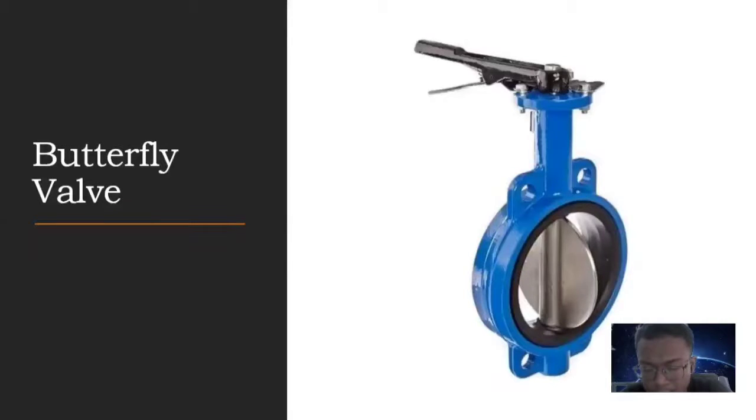Butterfly valve. A butterfly valve has a circular disc that can be rotated through one complete revolution. The circular disc has a diameter equal to that of the pipe. The valve is connected across both faces by two pipes with flanges. The circular disc is made to rotate around an axis passing through the vertical diameter of the disc. This type of flow control valve is used for controlling moderate flow.